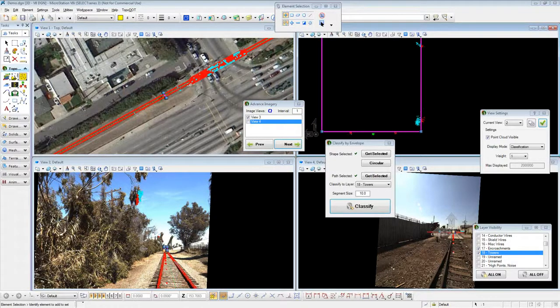Okay, here's what I'm trying to figure out, Ted. And this will go right in line with what Joe's asking. We have a series of bridges. They're in curves, they're cambered, and they're super elevated. So what we're trying to do is take the DTM of the 4.2 grade, drop it down our clearance of our rebar, create that next surface, and then scan the rebar and have it give us a cut fill map above that surface.